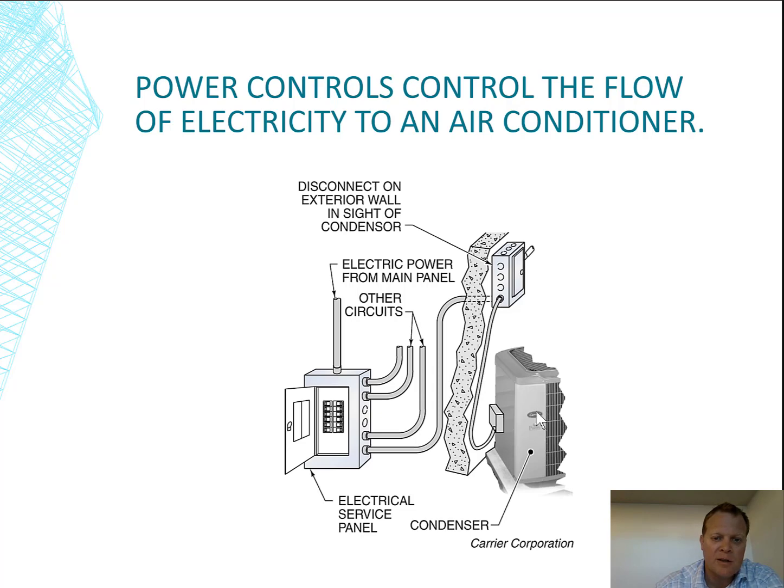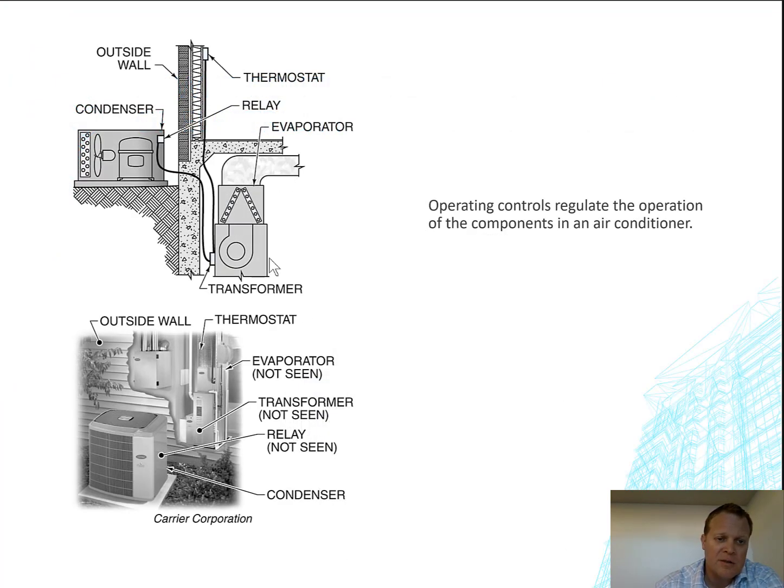We need to be communicating all this information back to the electrical utility, as well as the gas utility, for the BTUs used for the furnace need to be used in the calculation for the gas line. So there's some coordination that needs to happen early on during the permitting process or utility service agreements, that we need to get information to them so that we can size our utility correctly, both how much power and the gas meter size as well.